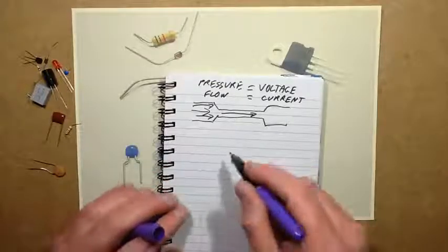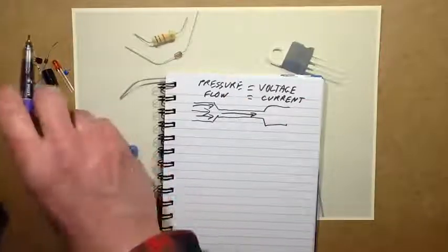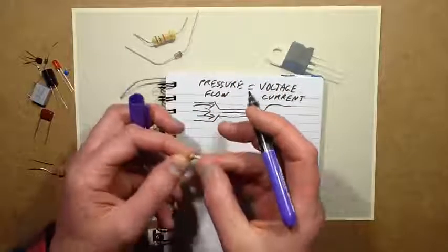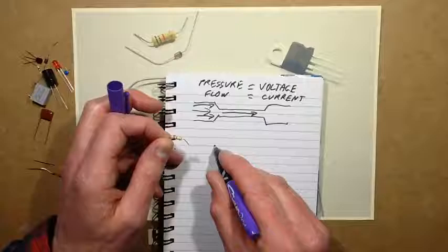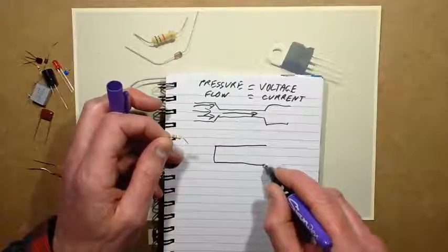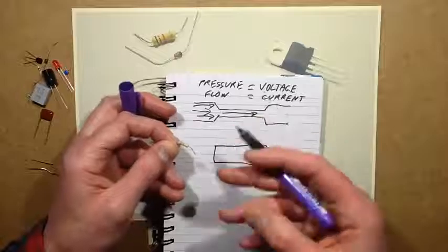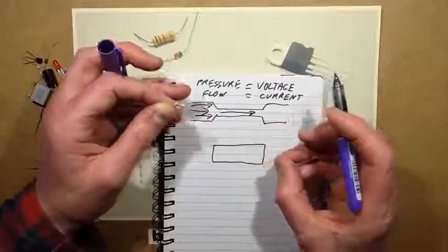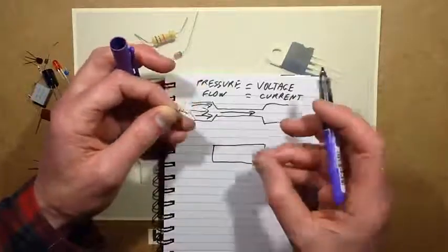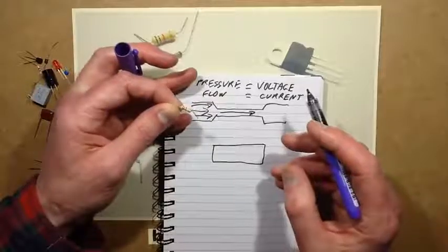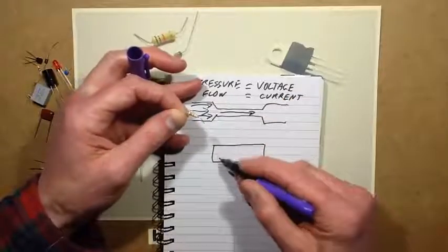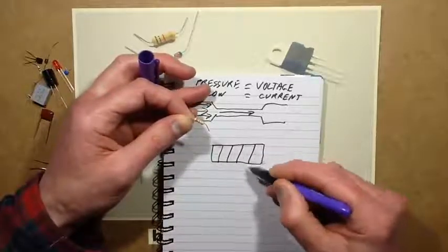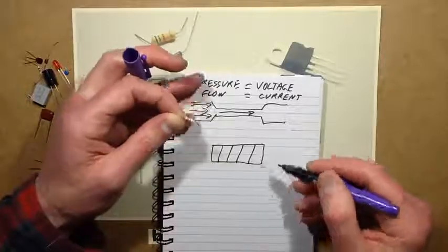Now the construction of a resistor is usually, in the case of these ones, this is a carbon film resistor. And you get metal film, carbon film, wire wound, but one of the most common is just carbon film or the metal film. And they have a little ceramic tube which is coated with either the metallized coating or a carbon coating up to a specific thickness. And the thicker the carbon coating on it and the type of the composition they're putting on it, the more conductive it will be. But then they can fine-tune that. They actually cut a spiral round it, and that creates a long thin path of the carbon, and that increases the value of the resistance.